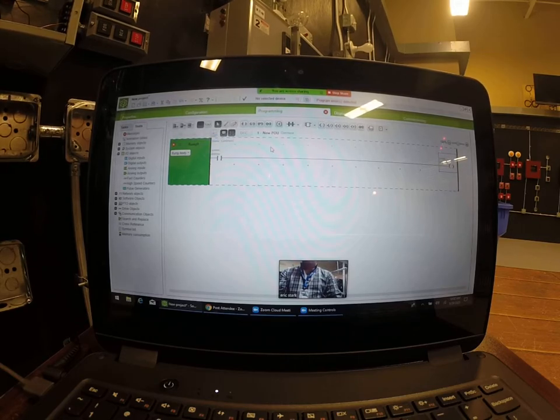So one thing to take note of is we've got one rung built. It resembles the motor control logic. We have an open contact to a coil, but like motor controls, nothing works unless it's labeled correctly. So at the top of your screen, you're going to notice where it says program error. It's because we're not finished.